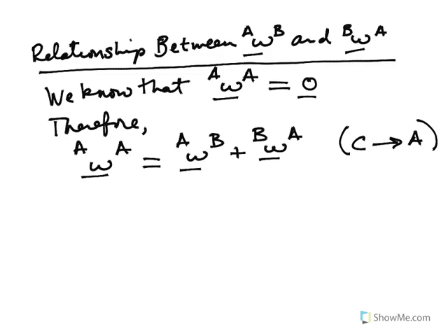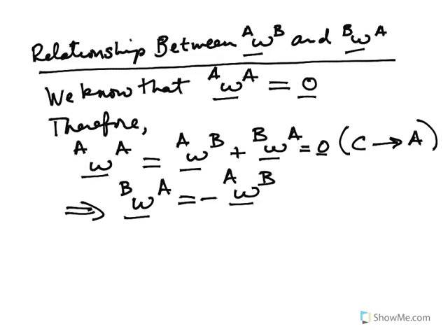So if I take that result, I know that that has to equal 0. So given the fact that that has to equal 0, I know that omega AB has to equal negative omega BA. So that's the third property that I needed to define. Now that we have these properties defined, we can actually start describing position, velocity, and acceleration, and we're going to need these properties in order to be able to parameterize that motion in different reference frames, in different coordinate systems. So we're going to wind up using these results quite frequently.